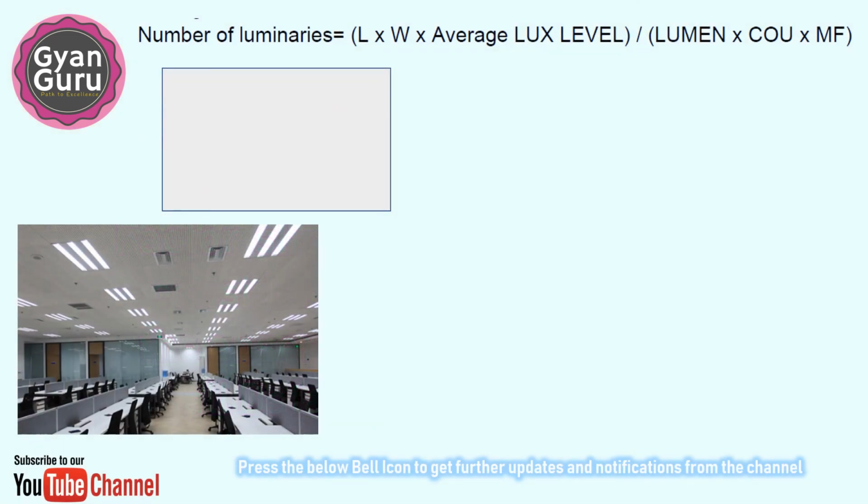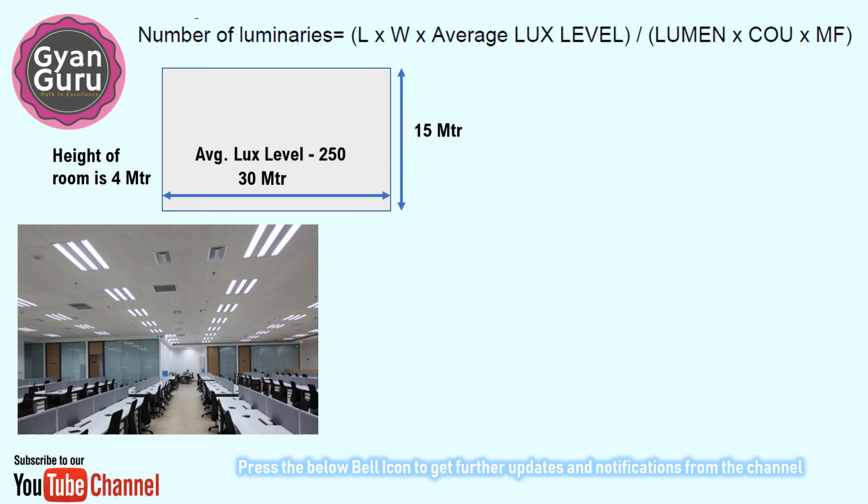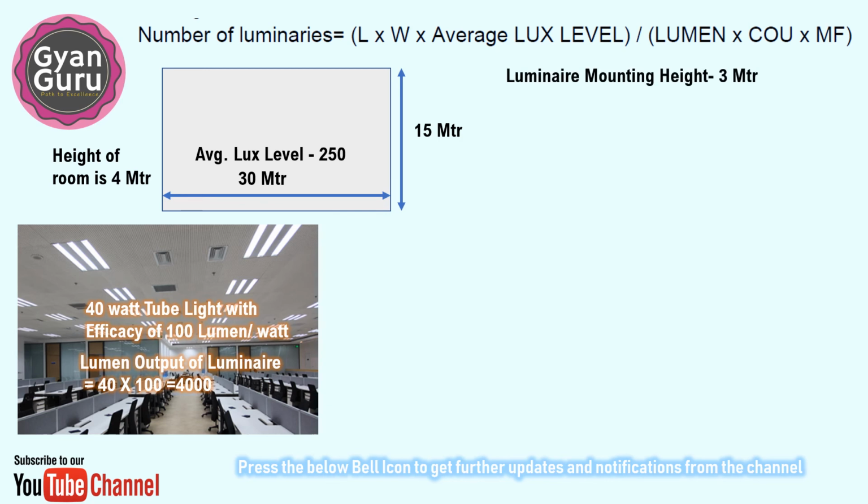Let's see how to calculate the number of luminaires in a room. Let us assume we have an office room with 30 meter length and 15 meter breadth, and the height of the room is 4 meters. Generally, as per standard practice, the lux level required in the office is 250 lux. Now let's see how many luminaires we need to illuminate the office space with a 40 watt luminaire having an efficacy of 100 lumen per watt. Hence total lumen output is 4000. This luminaire will be mounted at a height of 3 meters.